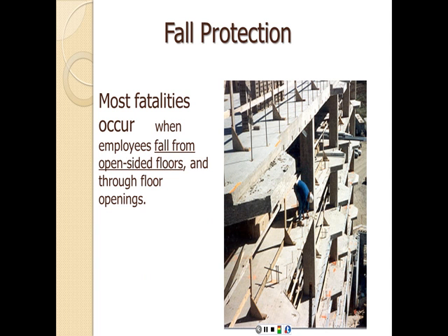This is very dangerous. We have several hazards here. We have a hazard of impalement because of these rebars protruding from the slabs like that. So if that person falls on the rebar, they can penetrate their chest and kill them. This is an open end. Obviously, he's standing beyond the guardrail, which does not have a mid-rail. So several violations here. He does not have any fall protection devices.